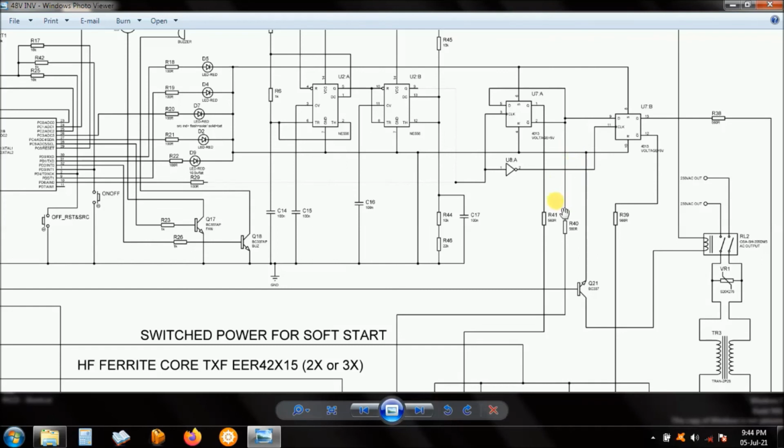You can choose to have pin number 2 or pin number 13 connected to the high MOSFETs. It still works, but this is one leg of the H bridge and the other leg of the H bridge, top and bottom, or vice versa, whichever way you choose.